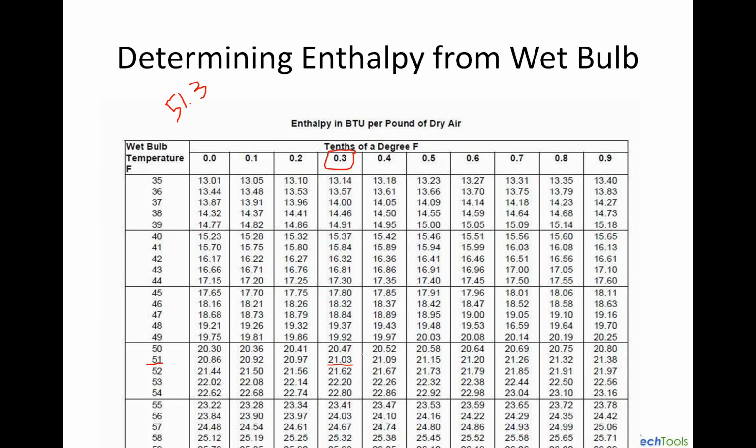Again, 1/10 of a degree of wet bulb equates to about 1/10 of a ton of cooling. So we don't want to have ones that are a degree or 2 degrees apart on the wet bulb, because it's going to drastically throw off our readings.